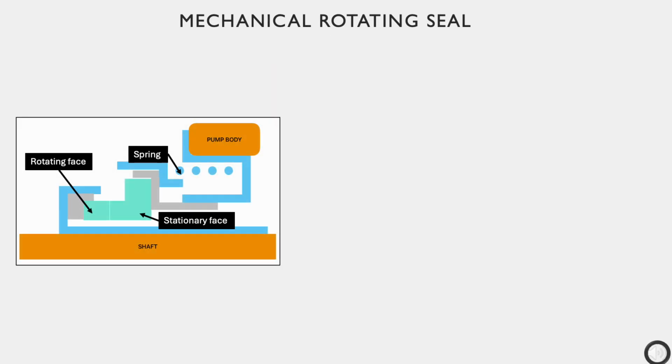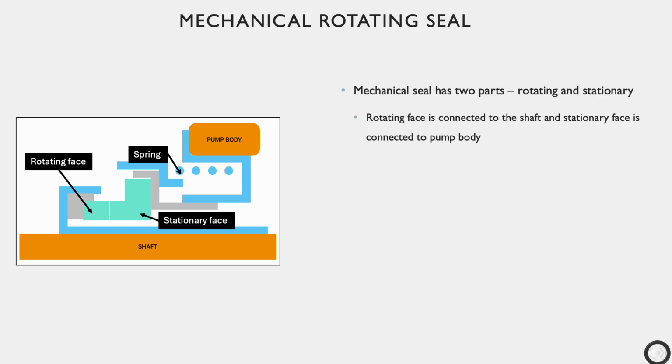The mechanical seal is another important part of the water pump. Pump leakage is common across the industry and mainly attributed to seal failure. This seal has two parts. One is a rotating part, which is mounted on the shaft, and another one is a static part, which is housed in the casing. A very small space, in microns, is designed between the two faces.